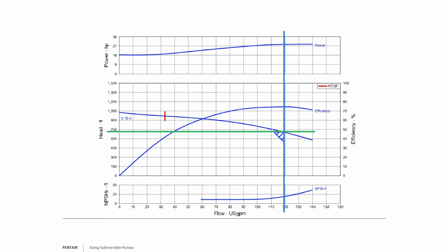I don't know, but I can guess. Now, the power curve, we're looking at that, and I call that about maybe 28. Okay, and that's that red line. I look at my gallon per minute usage, then draw a line, follow it over to my horsepower rated, and I'll see about 28. My best efficiency point, looking at that, I'll be guessing about 75% efficient.